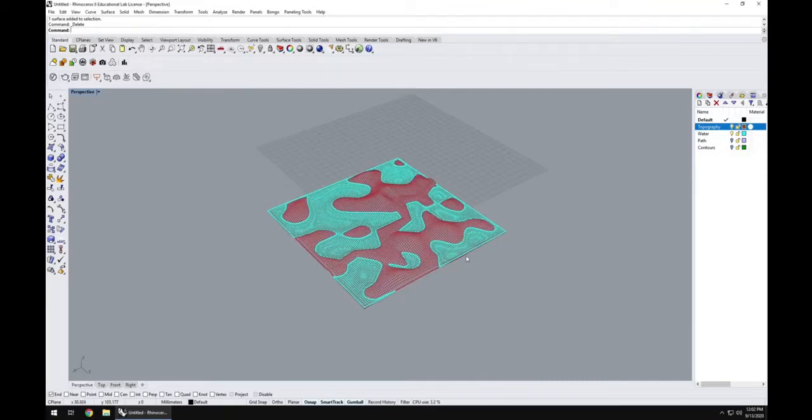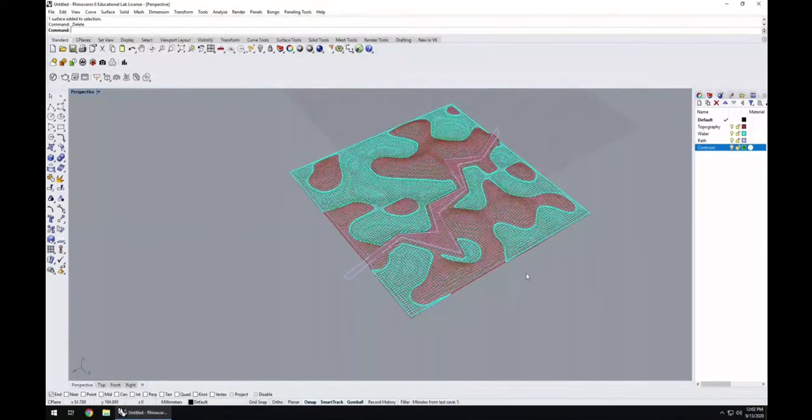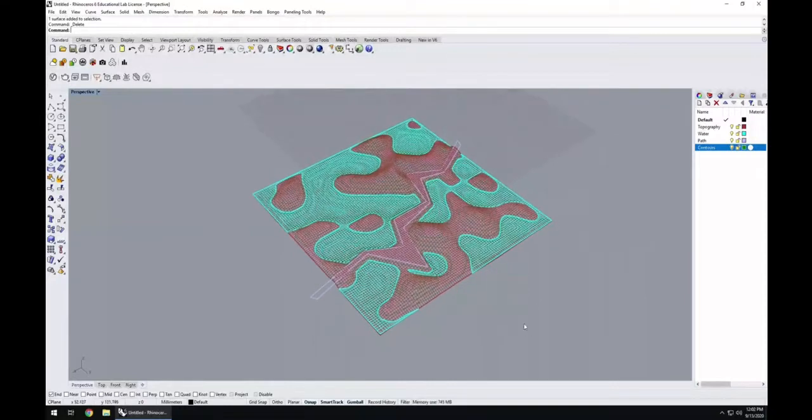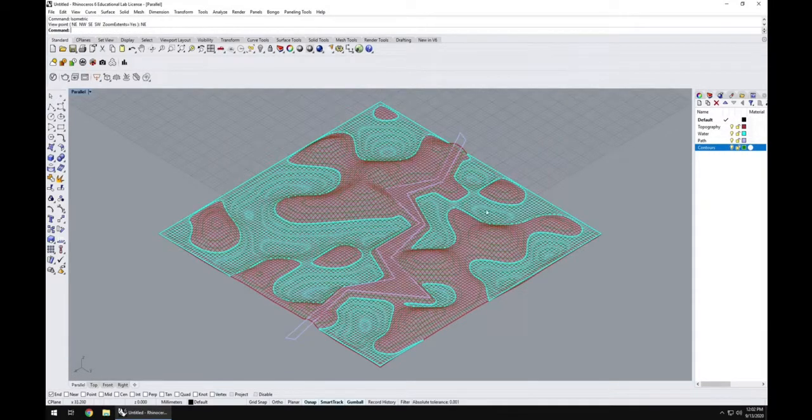Yeah, here we go. Once you have a clean Rhino model, now we want to make isometric drawings, right? In the command line, you just type in isometric, and the viewpoint is the perspective view of this isometric view. We're just going to do northeast, and there we go. That's your isometric view from northeast of this model.